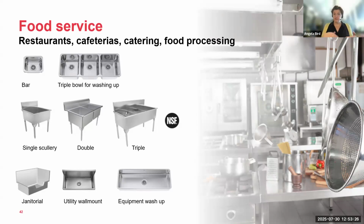When specifying a scullery sink for food prep, it's important to consider the inside corner radius of the bowls. Health units everywhere require coved corners rather than those 90-degree corners, like the inside of a box, because the food gets stuck in those corners and the bacteria will breed and it's hard to clean out. So having those rounded corners makes sure that it's super easy to wash all that food residue away. And if you're speccing a sink that is certified NSF2, it will ensure that your scullery sinks meet code for food prep.